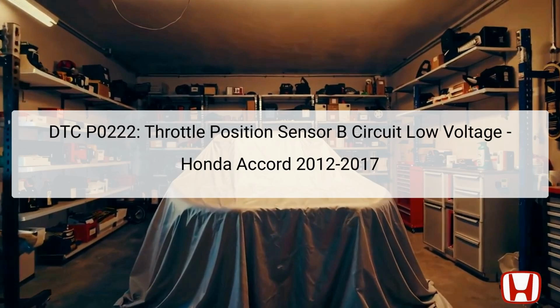The DTC P0222 error code is indicative of a problem with the throttle position TP sensor B circuit in the Honda Accord models from 2012 to 2017. Specifically, this error signifies low voltage output from the TP sensor B. This sensor plays a crucial role in regulating engine performance by informing the powertrain control module, PCM, about the throttle valve's position. If the PCM receives a steady low voltage signal from this sensor over a period, it interprets this as a malfunction and subsequently triggers the DTC.